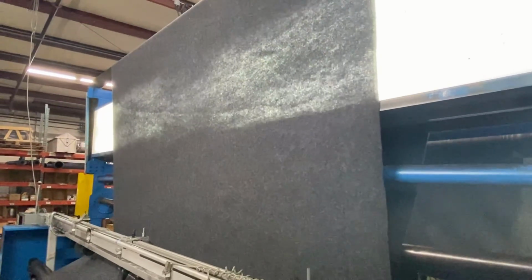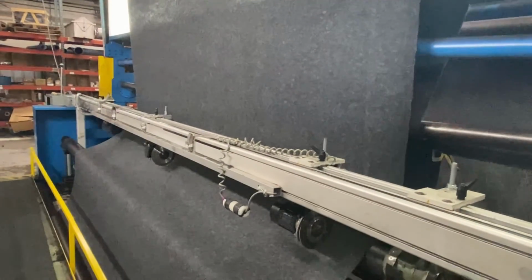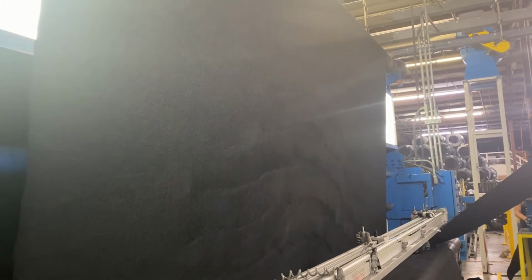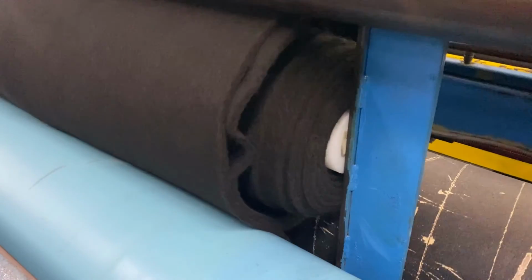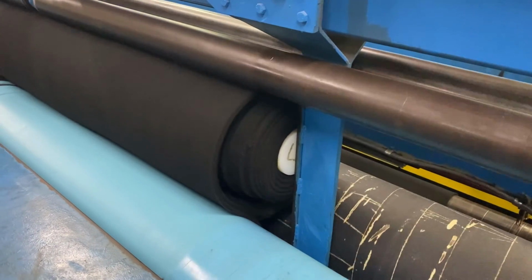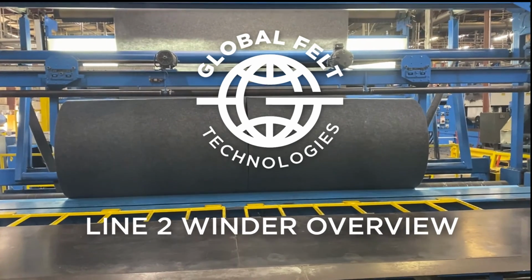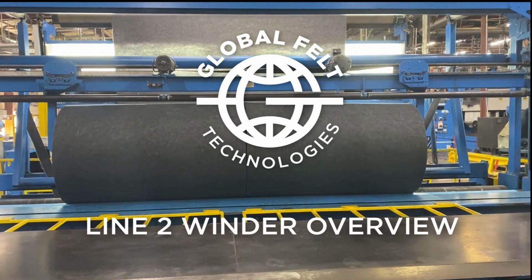Lastly, it is very important to look for visible defects while the material is running. It is critical to produce and ship first quality product to our customers. Be alert to identify issues such as needle lines or drag backs, needles, holes, lapper quality issues, neps, contamination, or any other noticeable flaws in the material. Let your operator know immediately if any of these visible defects are identified. This concludes the winder process of producing needle punch felt on line 2 at Global Felt Technologies.